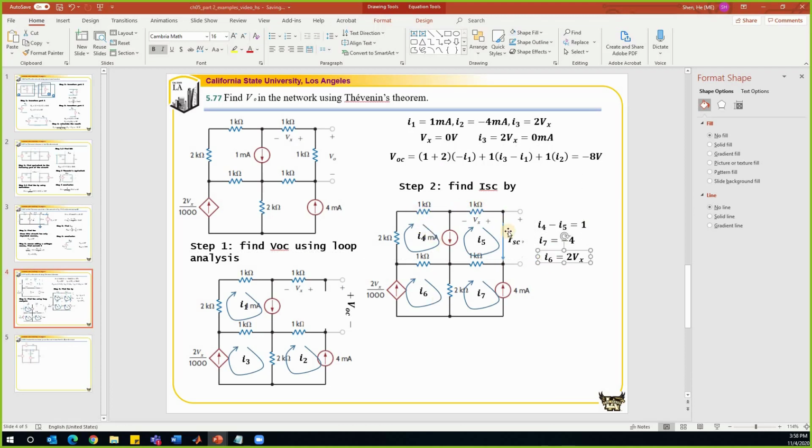At the same time, we are short of one equation, so let's use the general loop method to find an additional equation from this super mesh. The super mesh is obtained by opening this shared current source. It opens up another mesh, which we define as a super mesh. So this is our super mesh. We'll write the equation for this super mesh by using KVL.